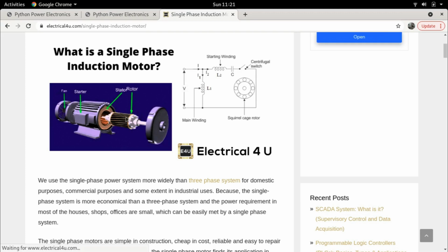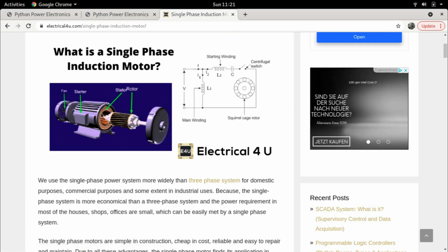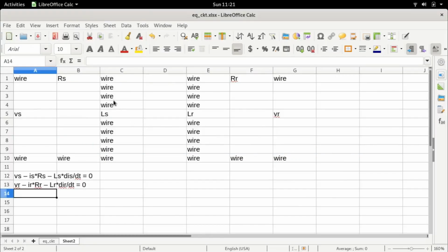Similarly, the rotor will also produce some amount of flux which leaks away from the air gap somewhere else, right? Don't worry about where. It could circulate somewhere local, whatever. It just is not doing anything useful by producing a flux in the air gap. This exists for both the stator and the rotor. So what we can do is split up this inductance as LLS and LMS. And the same goes for the rotor as well.